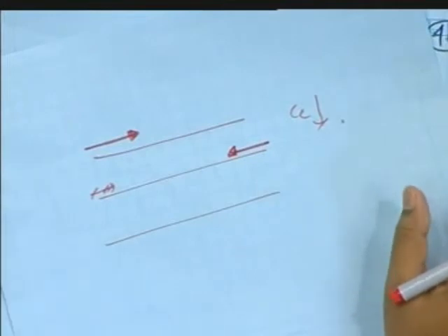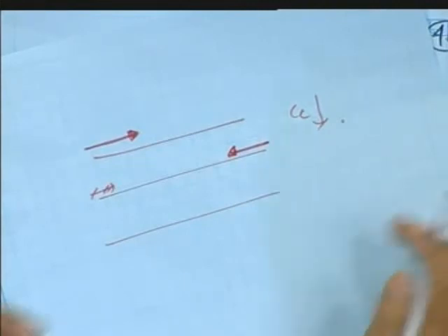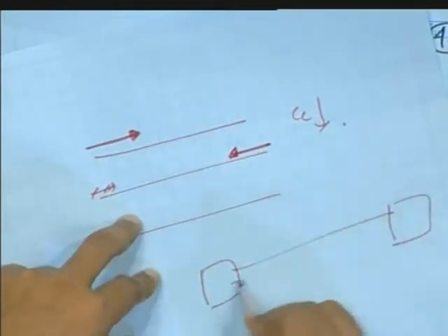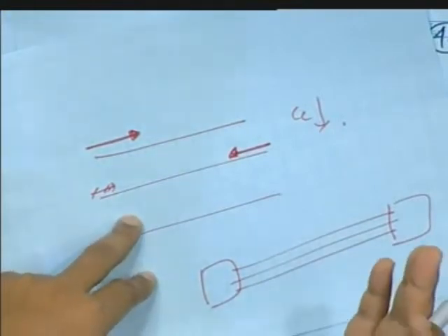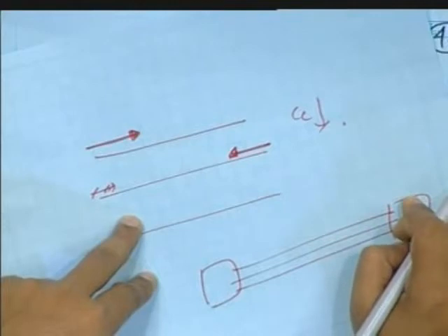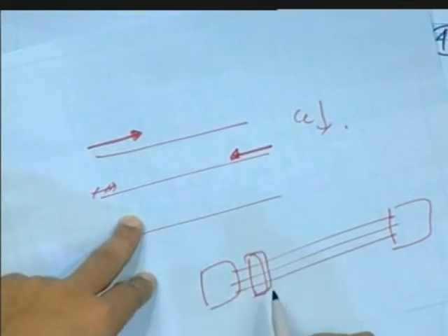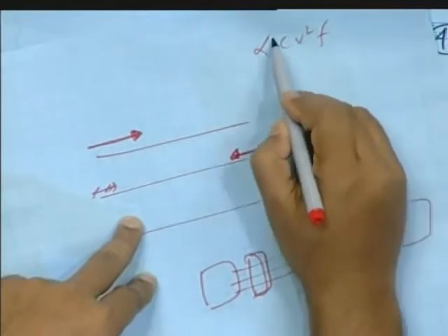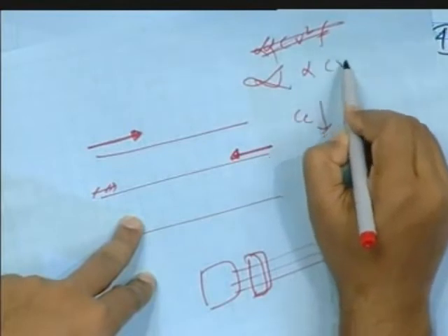Okay, and when you do the bus coding, when the bus capacitance is pretty high, basically say here is one peripheral, here is one peripheral at sufficiently long distance. So you are communicating through long buses. Long buses means what? Larger capacitance. It has to drive it. Correct. So then only you can go for the bus coding. If it is placed here itself, there is no point. Correct. Power is proportional to C V square F, and there is proportional to alpha C V square F.